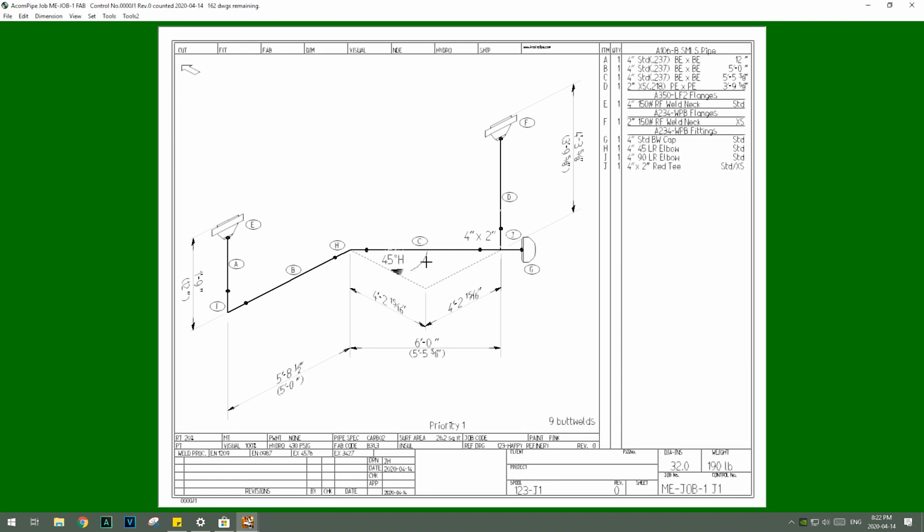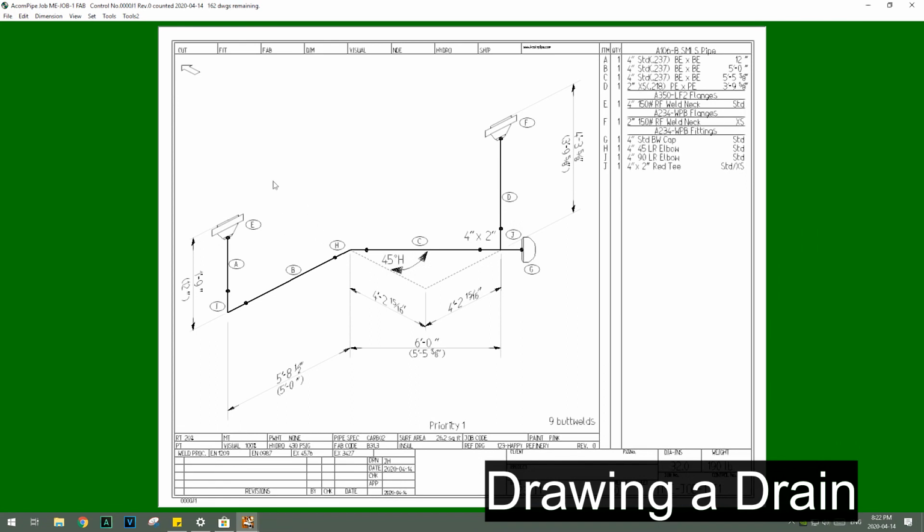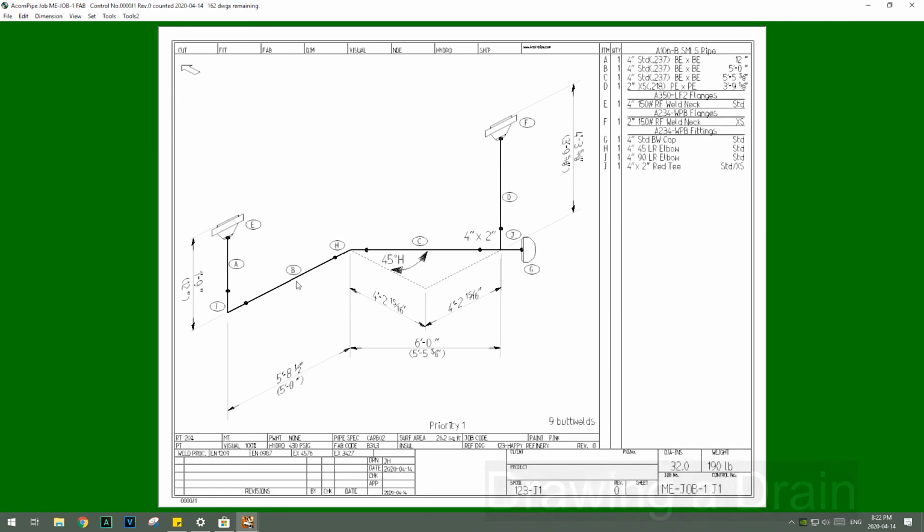Now there's a little trick here because it's only going to draw one arrowhead unless I hold the Shift button down. So I'm going to hold Shift down now, click on the left mouse button, and that'll put a 2 arrowhead arc.